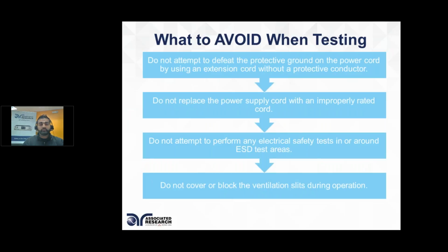Few more things here: you want to make sure you don't defeat any ground protective circuits. Like I said, the ground pin on the tester, make sure it is plugged in, and do not use extension cords that have broken ground pins, to make sure the product or the tester itself is electrically safe and sound.